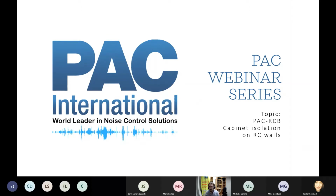Today we're going to talk about the PAC-RCB. It's a new product that we've been developing to really solve a long-standing acoustical issue in construction. Like I said, one that I ran into a lot as an acoustical consultant, and it is how to handle cabinets and other heavy loads like TVs, headboards, nightstands, grab bars, all those kinds of things on walls that have resilient channel. How do you support those things, provide the structural support for those heavy loads, and still provide the acoustic isolation of the resilient channel? So that's what we're going to go into today.